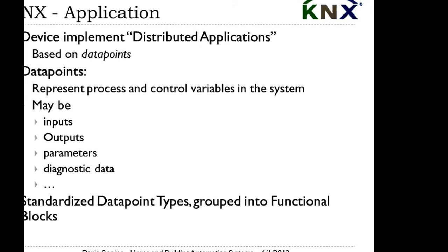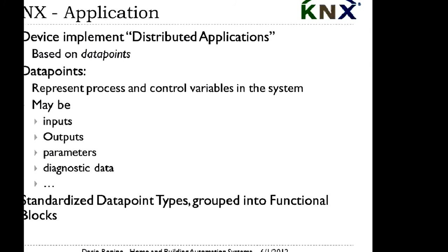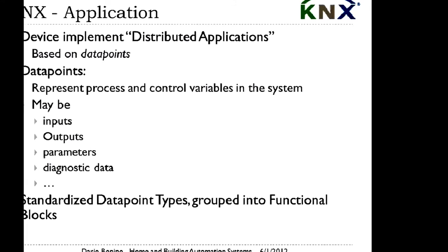Let's understand how the communication between devices works. The idea of KNX is to build a distributed application. So here we are not speaking of switching on lamps or controlling shutters, opening doors. We are speaking of applications that might include also switching on lamps or closing doors, but in general they are designed for doing some general task altogether. For example, safety or fire detection. And this is the application, and then all devices participate in the application. And this participation is based on the concept of data points.